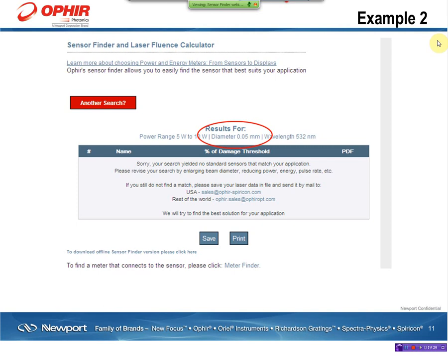Now, okay, in this example, let's say a laser marking system. What does a laser marking system do? Focuses a beam down so that it's small enough so that it can burn letters into maybe solid steel or something like that, which means it's zapping material. Well, if it zaps material to mark it, it might also zap material on the sensor and damage it. And if we think about it for a few more seconds, we realize that the beam needs to be focused to do its work. It doesn't need to be focused for the purpose of measuring it.